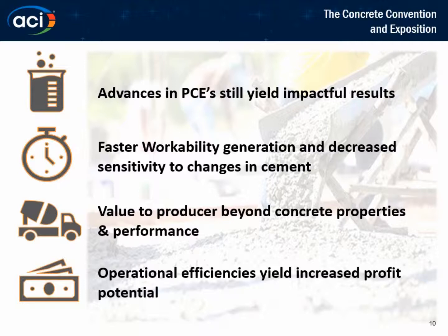Yes. Any differences in air entrainment? No, no. We tested it with both natural and synthetic air entrainers, and the impact was very similar in terms of not only the hardened properties of what that air entrainer combination with the PCE can produce, your mix design, how that dictated, it did not deviate from the standard reference, which was a standard PCE polymer.